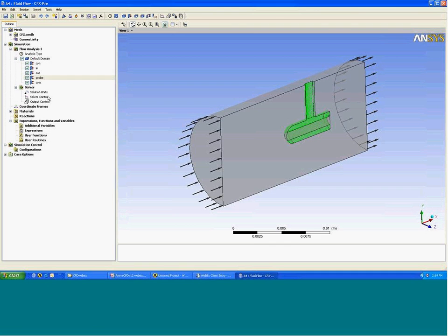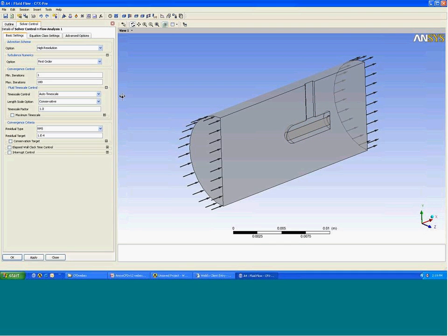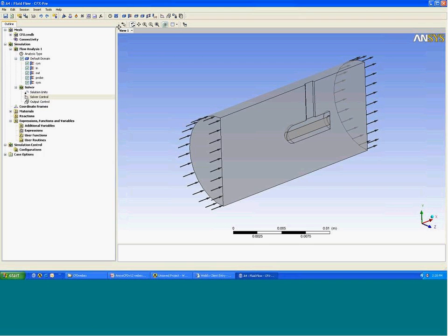So the next step, we'll be generating numerical parameters. And I will use the default scheme provided by CFX. In this case, it's the high-resolution scheme. It provides second-order accurate solutions everywhere throughout the flow field. And I'm going to assign 100 iterations, or when the residual reaches 10 to the minus 4, which is small, representing roughly about 0.1% oscillation of the flow value, which can be taken as a steady-state approach being achieved. So right now, I have completed the setup for the simple calculation.